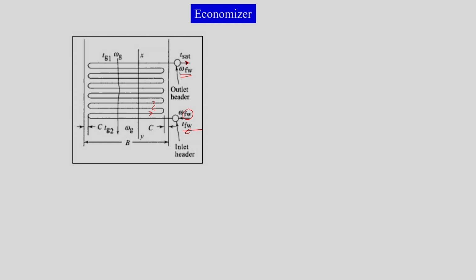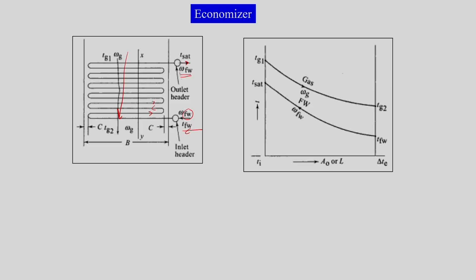However, we can see that we have flue gas which is coming in this direction and heating the water. Our idea in this schematic is to design the number of coils required for the economizer in the water tube boiler. Basically, this is a counterflow heat exchanger where we are heating the feed water from low temperature to high temperature along this length, and the flue gas will lose its temperature from this to this, and get cooled, but at the expense that it will heat the feed water.